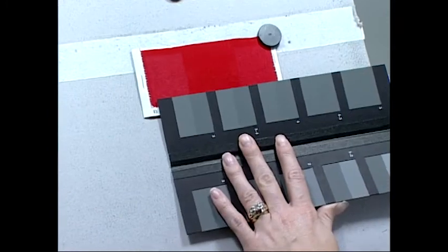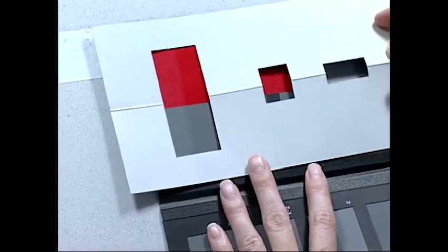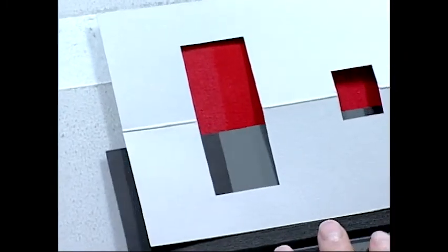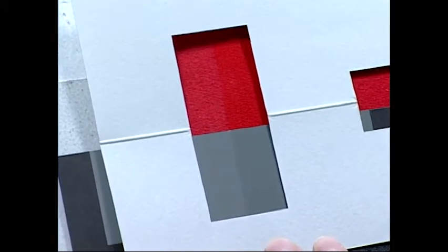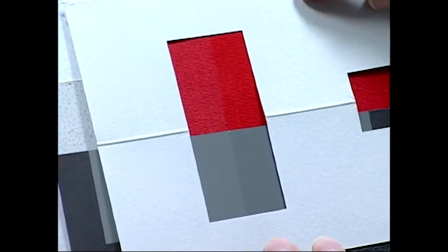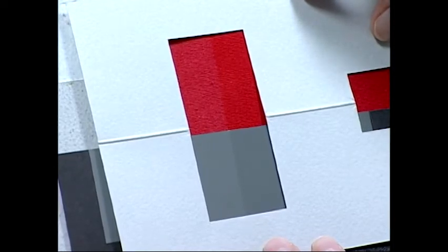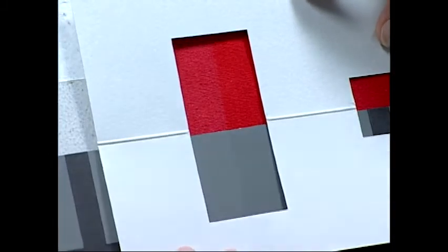The gray mask provided with the scale is placed over the samples and the scale to eliminate any influence of the surrounding areas. The surfaces are illuminated with a daylight simulator of standard values. The light incident upon the surfaces is at a 45-degree angle and the direction of viewing at 90 degrees to the plane of the surfaces. The tiles are moved under the exposure window until the rater has determined the level of color change.